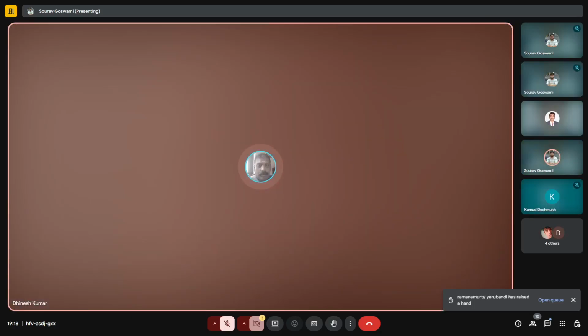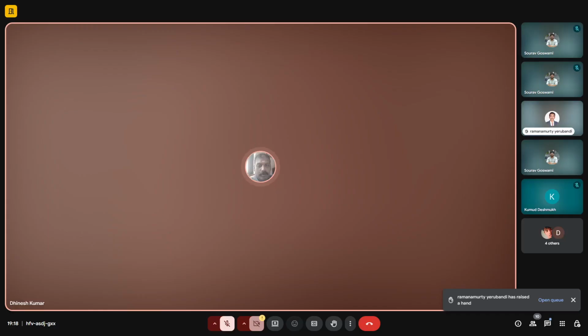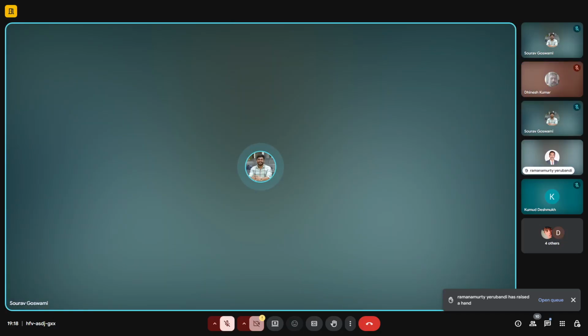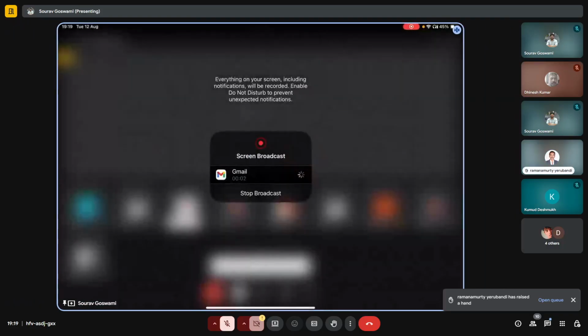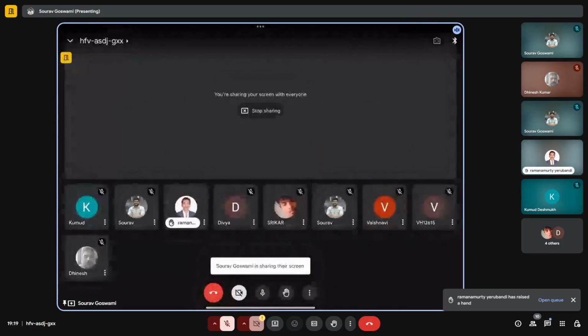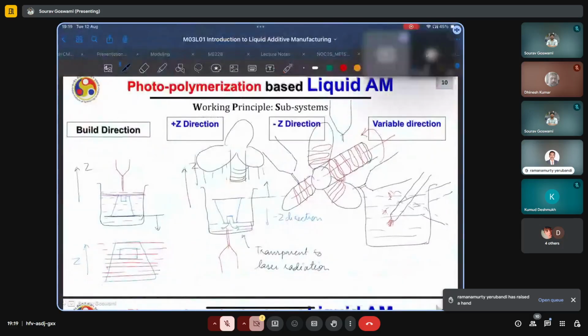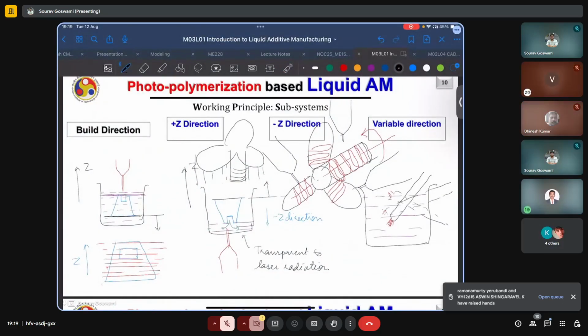So this support structure is not required for powder parts or wire also. Typically, it may not be required for powders. Even in that case, we will encounter cases where it will be required. Definitely at the bottom of the part where it is connected to the build plate, where it acts as a machining allowance. And for certain complicated parts or large parts, you may still require support structures even in the middle of the part. But yeah, there are certain applications where the surrounding powder itself will act as a support structure, but not always.